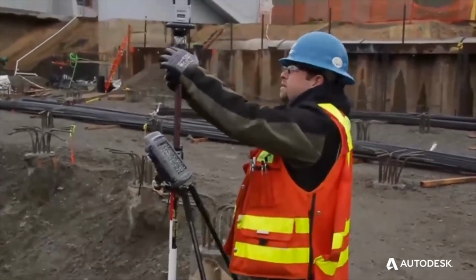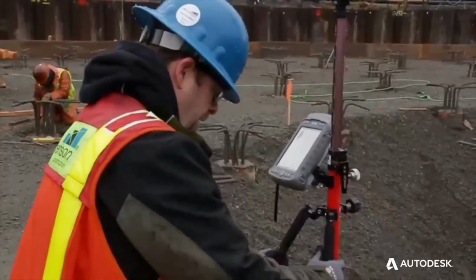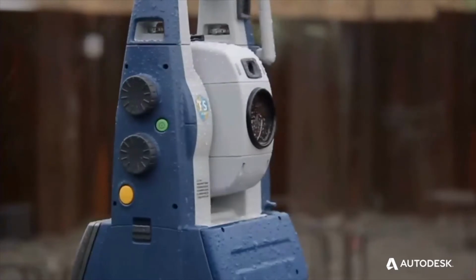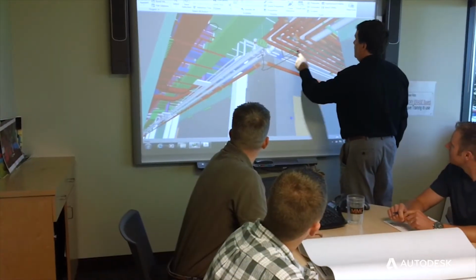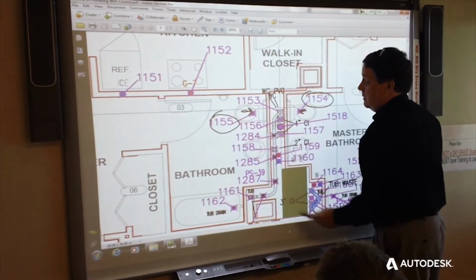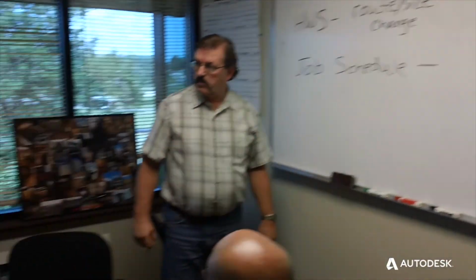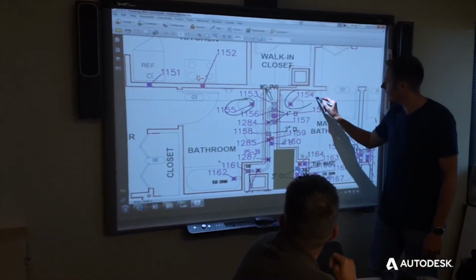They send that information back to us, we load that information back into our Revit model, and we know the new location of the item so we can easily as-built the model to the location that the field placed it. So the drawing we give them is what the owner gets. Those are their as-builts. Not only being able to extract the points from Revit, but also using it in an AutoCAD format. So that way, any 3D files that we get from a plumber or electrician in the CAD pipe or any CAD format, we are able to extract the points and export them in the survey coordinates.